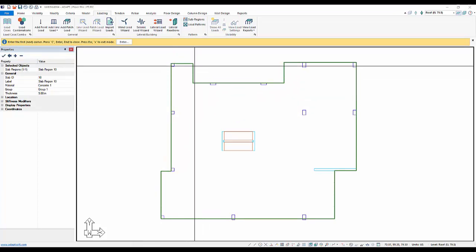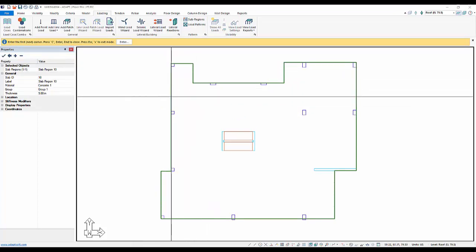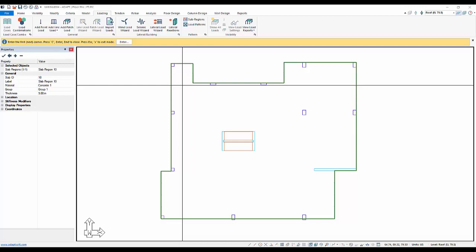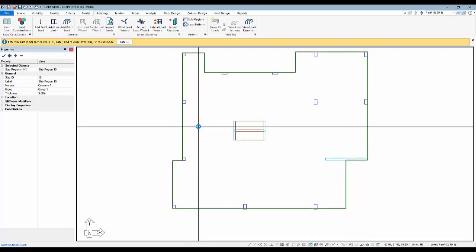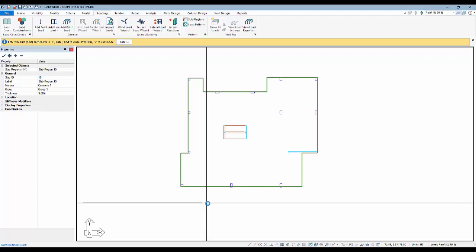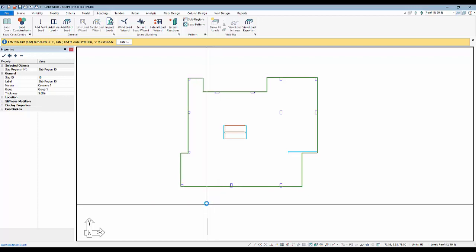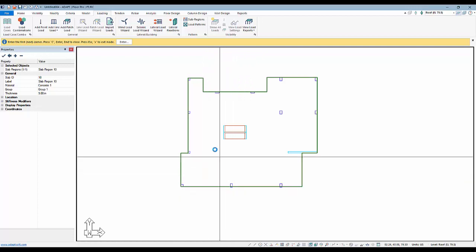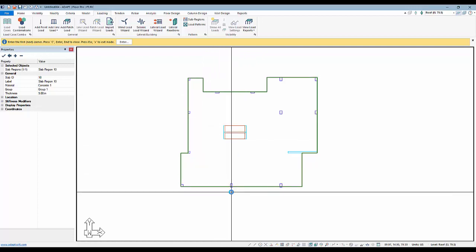We can create closed polygons to generate the region. So we would create multiple closed regions that represent each specific area that can be assigned as part of a pattern, or we can use polylines, and if we use polylines, the program will then break those into these regions. So we're going to use the option for polylines, and I'm going to use kind of the frame lines to associate these polylines to.